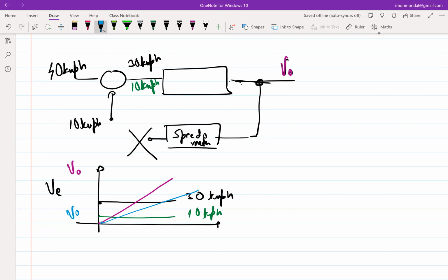So, which essentially means that your input is a step. Input is a constant which is not changing with time, but your output is a ramp, and the slope of the ramp is dependent on the input, right? So what type of characteristics is this? What in terms of time, I mean, what is this block supposed to do? It's supposed to integrate, right? Input is constant, output is slowly ramping, right? And this integration also has a proportionality constant.